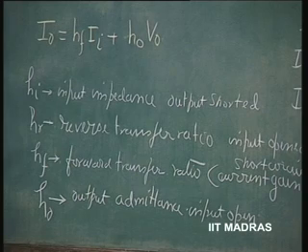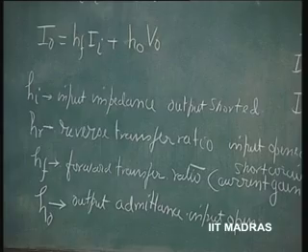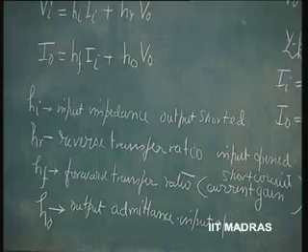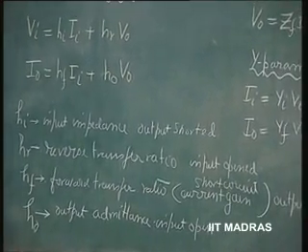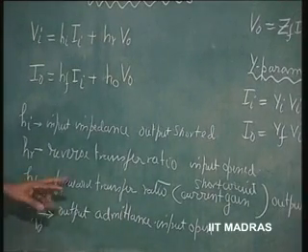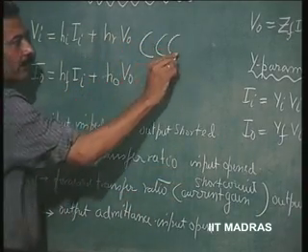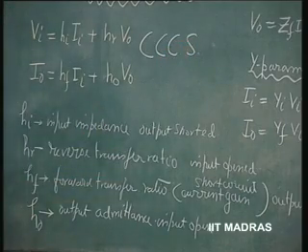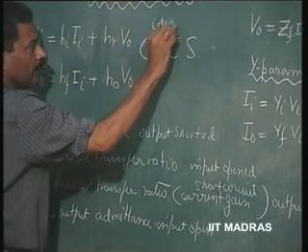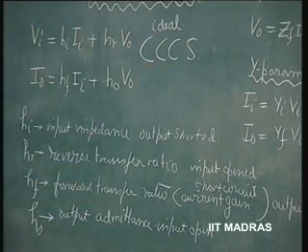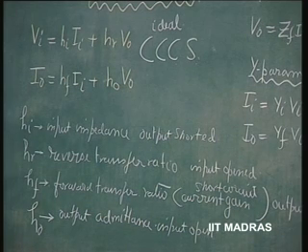So, these are very important parameters, that is why they are so important. We are likely to discuss the amplifier which this parameter normally represents, and what is the amplifier that normally represents? Obviously, you have seen here forward transfer ratio is a short circuit current gain. So, this is nothing but current controlled current source, ideal current controlled current source, which is what is our bipolar junction transistor.